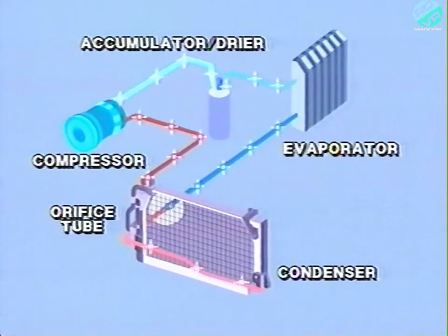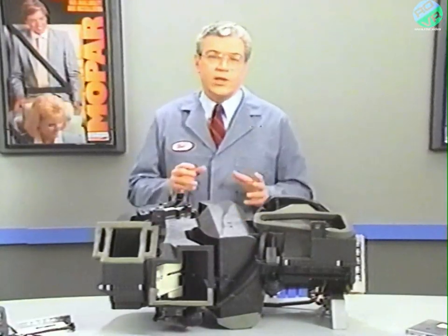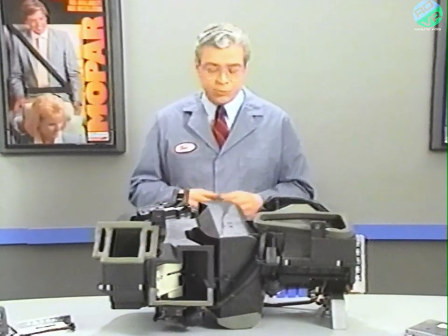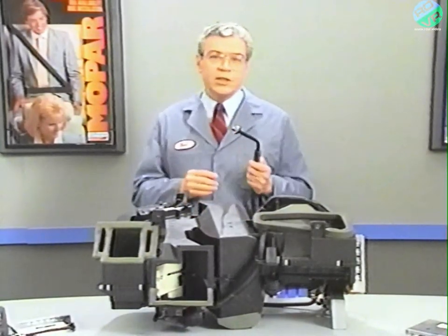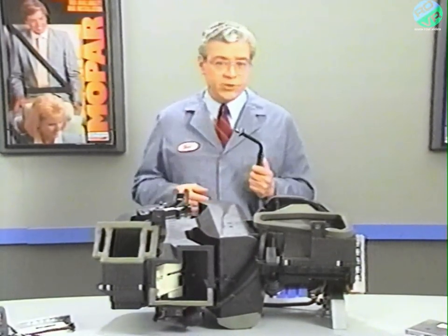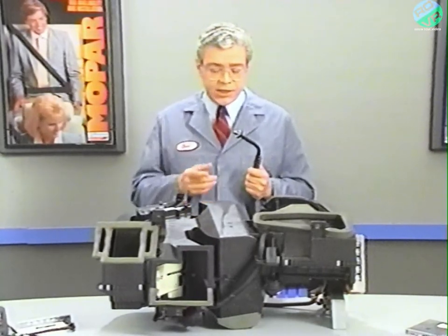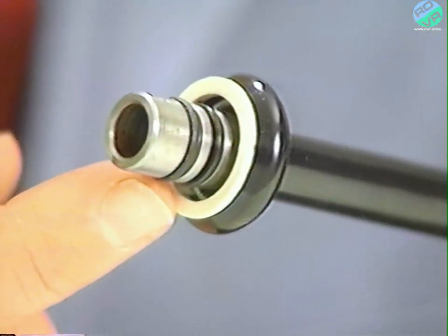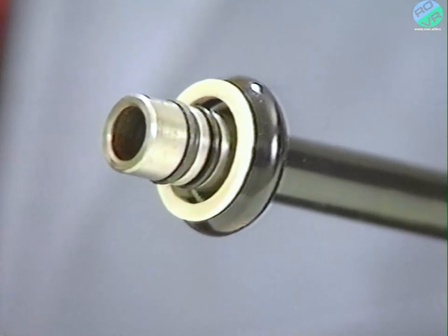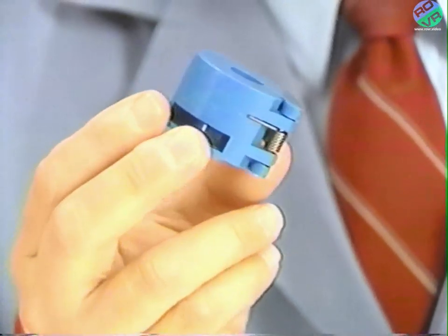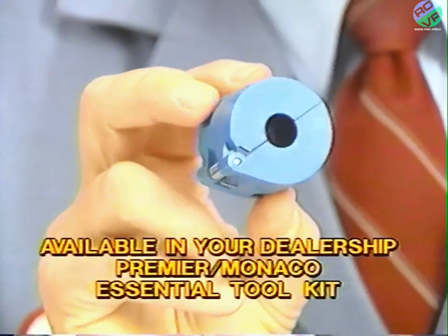into the evaporator. If you have occasion to replace AC components on a Premier, you'll find that the spring lock couplings are a little different from connectors you've seen on other systems. The coupling uses a garter spring and cage to lock the flared end of the female fitting over a male fitting. Disconnecting the couplings requires the use of a special tool.